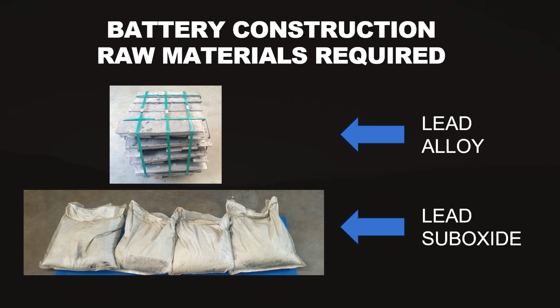When discussing lead alloys, the type of alloy used depends on the application of the battery and the specific type of battery. Now, alloys are mainly used to cast grids. The grids are the current conducting structures and they are cast to hold the active material. In pasted plate batteries, they are of the mesh type, and for tubular plate batteries, the positive grids have a spine structure.